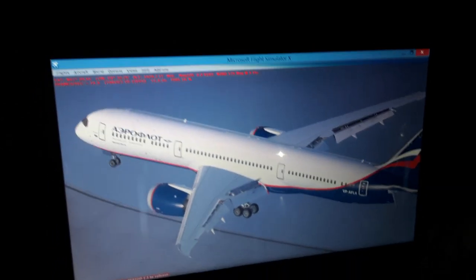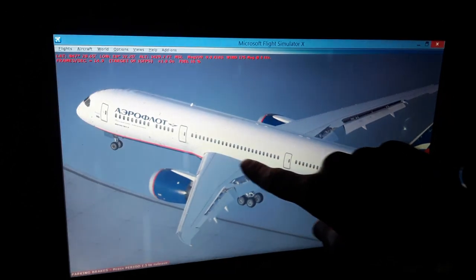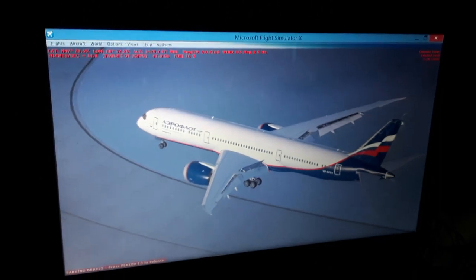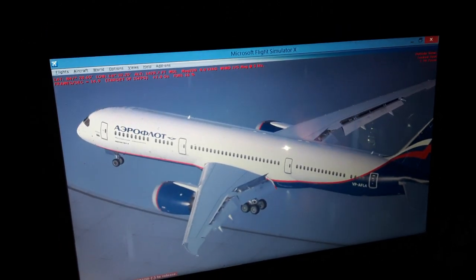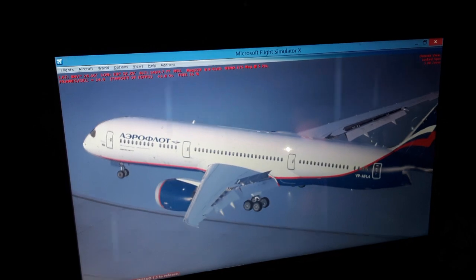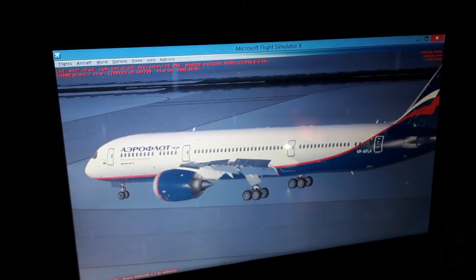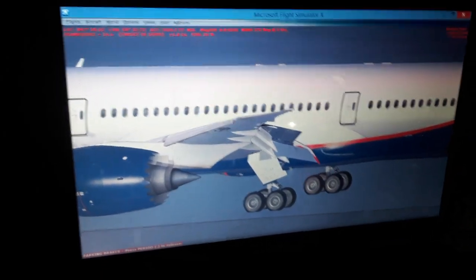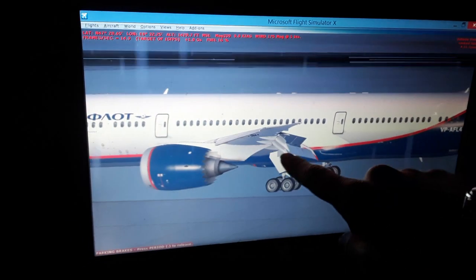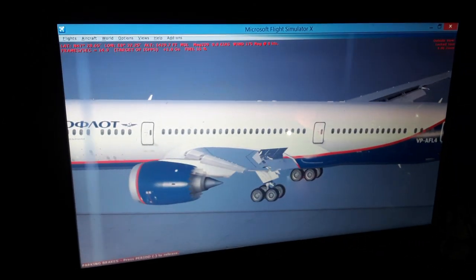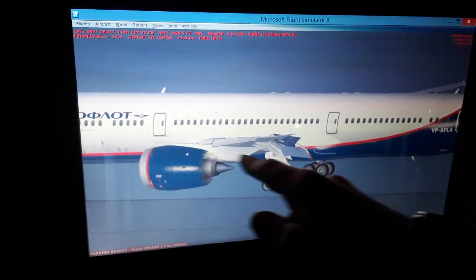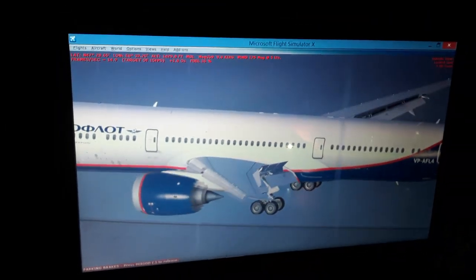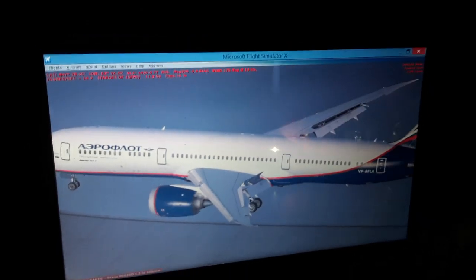is where the maximum aerodynamic lift occurs in the wings. Behind it is the center of pressure, and also we have where the stall will begin approximately in flight for an angle of attack that is given, and for an airspeed that changes depending on the attitude of the aircraft and whether we have flaps or not. And we have also here the altitude of flight. We have the bottom surface of the wings, you can see it's more flat, and we have the flaps extended, so as we accelerate for takeoff, the airflow is moving much slower below the wings, so we have higher pressure, which pressurizes the wings up into the air with the weight, and that keeps the aircraft airborne.